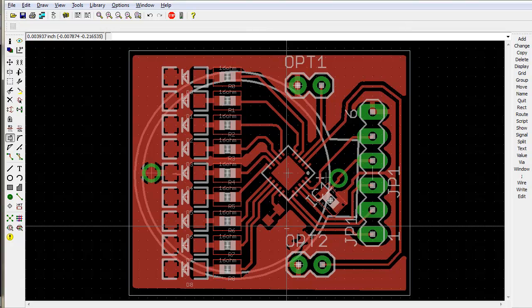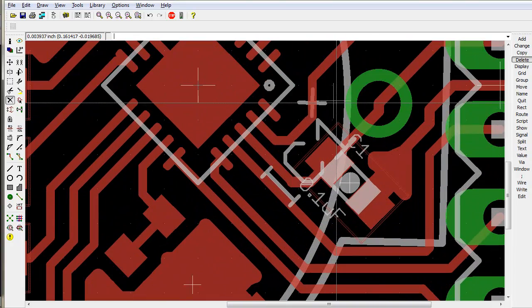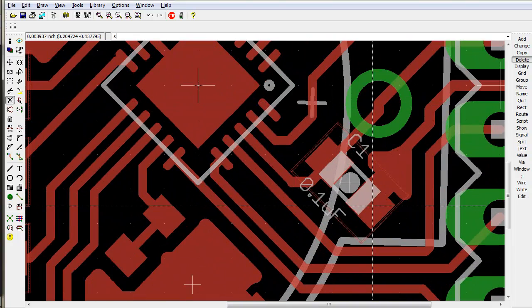smash some of these parts. Smash these guys. Smash these. Because I don't want the silkscreen labels. Yeah, there we go. It just wasn't hitting. Let's smash the ISP as well in the middle. We're not going to have that, because there's 2 of them. We don't want that. Let's smash this guy.